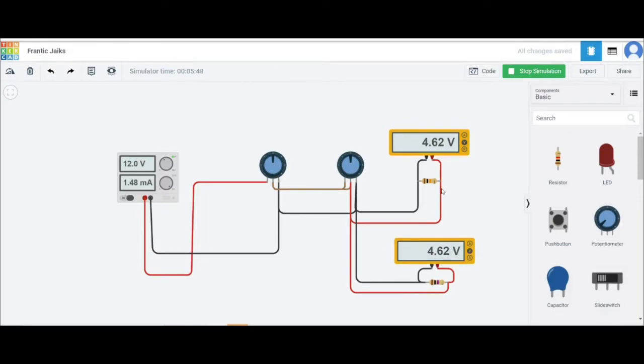This means the meter having the highest internal resistor will be more suitable for measurement, because if we have a lower internal resistance, then the reading will be affected.